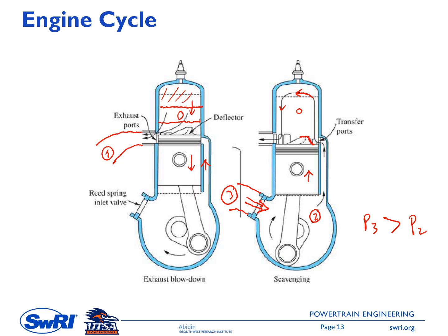If you talk about the 2-stroke engine, usually it's very popular in racing because you just would like to have a high power density and you don't care about the engine efficiency. And recently, this 2-stroke engine is also used for large engines, because usually large engines operate at low engine speed, and it is at low engine speed that the scavenging process is better. So it will have a higher efficiency of the scavenging at low engine speed.